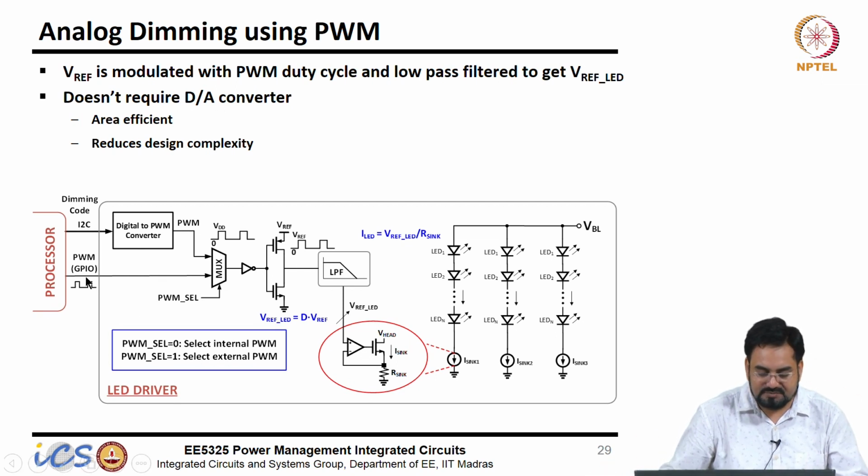So this GPIO will have a different level, and I know my full scale voltage is Vref here. So I can level shift this duty cycle to Vref.